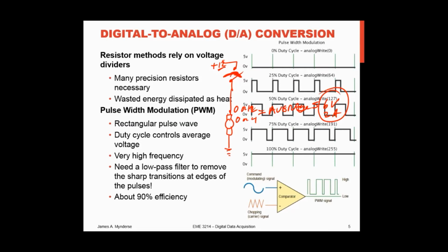Kind of hard to read when I write on top of a drawing, but I don't have much room to draw. So when I do this, if this is a solid-state switching device, when it's on, I may get a voltage drop across, say, of 0.2 volts, and the current is 4 amps instead of 2. 0.2 times 4 amps equals 0.8 watts to dissipate across that device. It's still some heat dissipation, but it's a lot less than the 12 that we needed the other way.